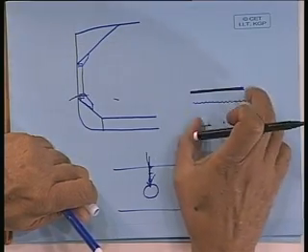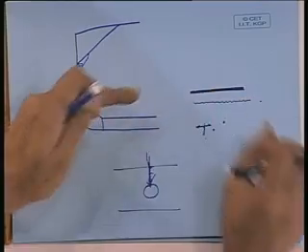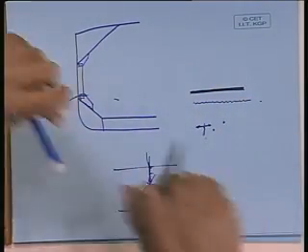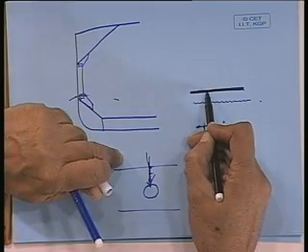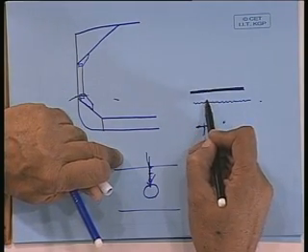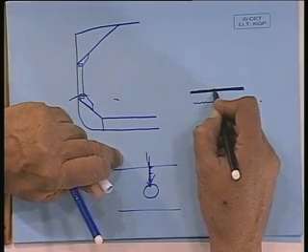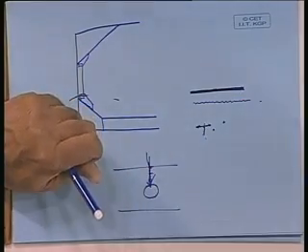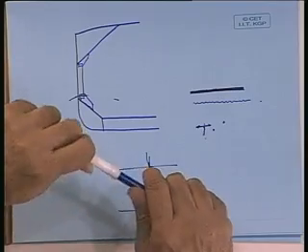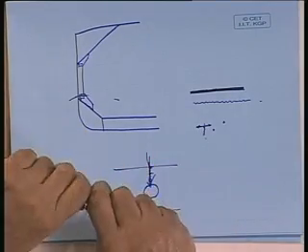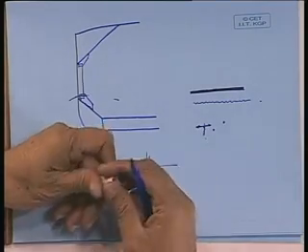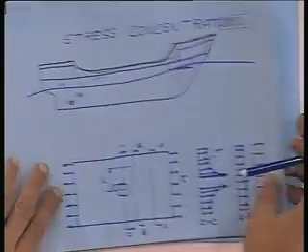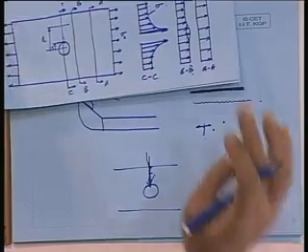When you are trying to flex this, either in tension or compression, the two must expand or contract together. If the expansion coefficient of this is less than this, or the elasticity, then a crack will develop here, and the corrosion will start from that, and pitting will take place. So though this is a chapter on corrosion, one finds that this theory can be applied to surface cracks.